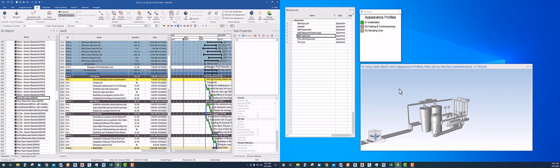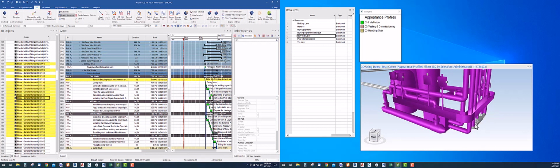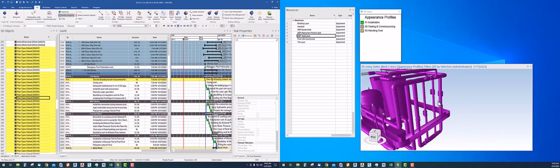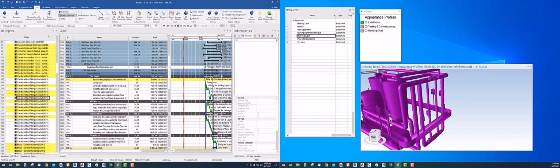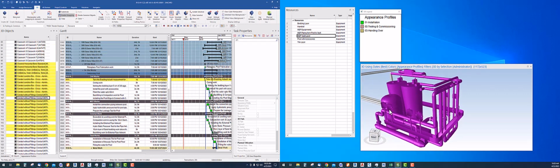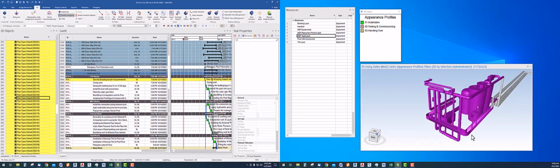Now the second thing is, I can select all these equipments and put them in MEP equipments. So I will press Control, create a window. When I create a window, everything is selected. Pipes also. Whatever is visible, that is selected. Whatever is not visible, that is not selected. So you need to zoom in and select one by one, either by pressing Control or simply left clicking. See, these are not selected, these are not selected, correct? This is also not selected. I will select everything.